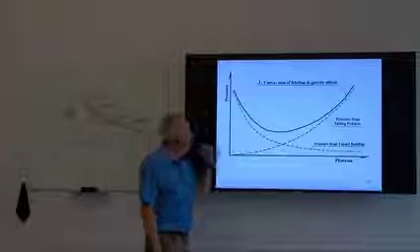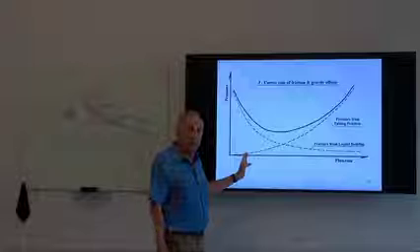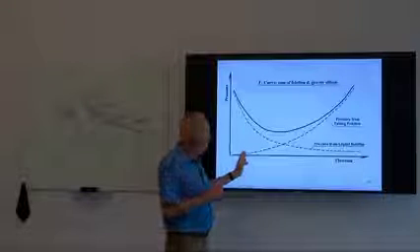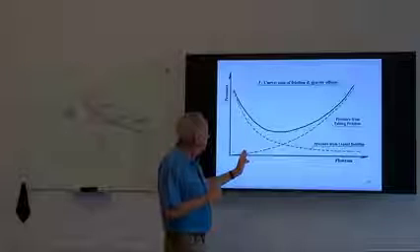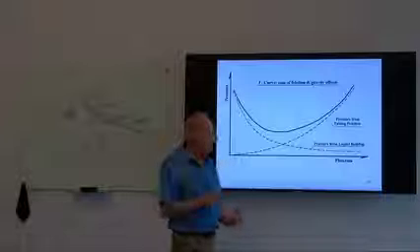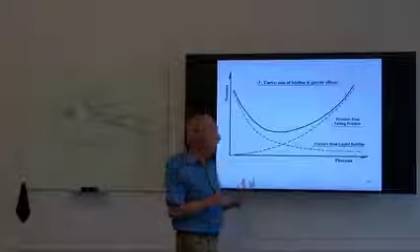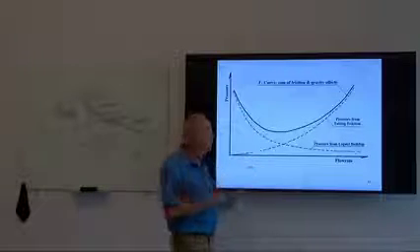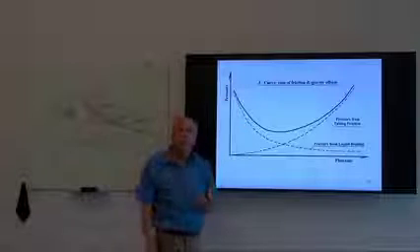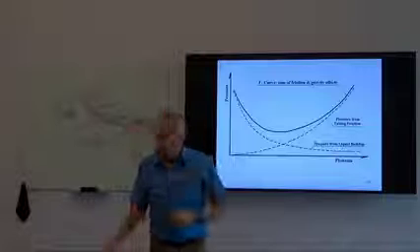So at very low flow rates, friction is not doing a very good job of maintaining a turbulent, well-mixed regime, but it also means that our liquid is very dominated by gravity, and it is getting pulled back down, and it is creating our bottom hole pressure. That's, by the way, what this represents, our flowing bottom hole pressure.